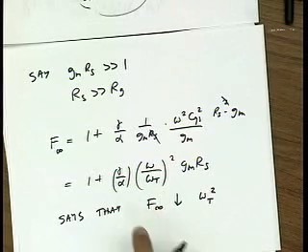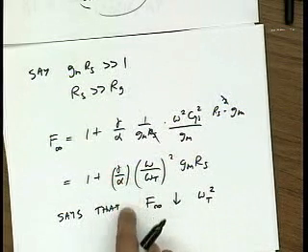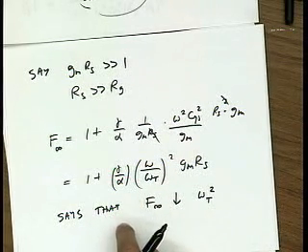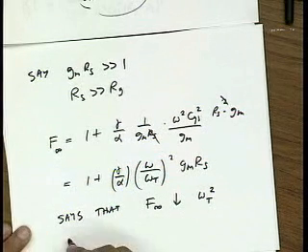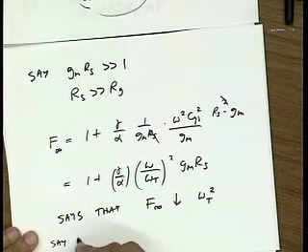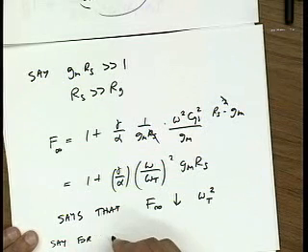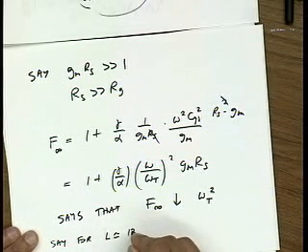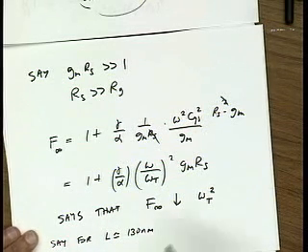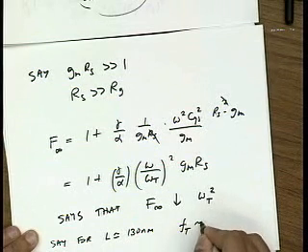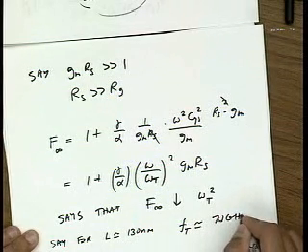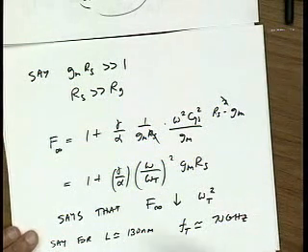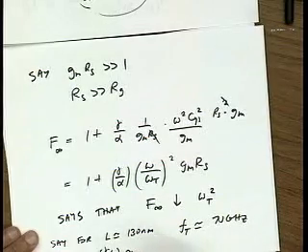And so even though gamma over alpha is larger than its long channel limit of 2/3, say, for a 130 nanometer device, FT is approximately 70 gigahertz. Gamma over alpha is approximately 2.